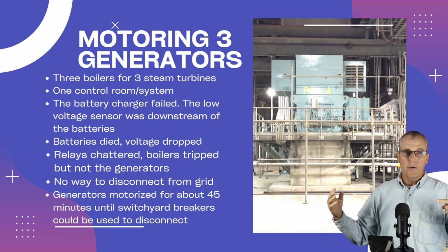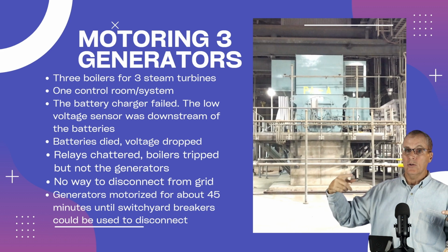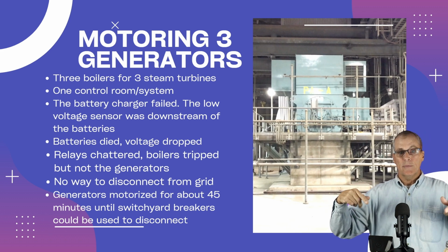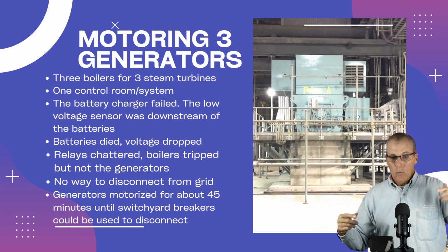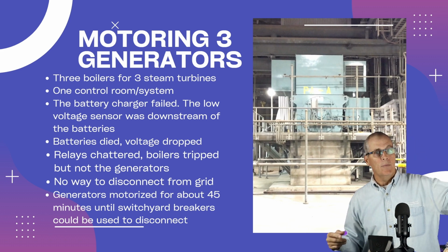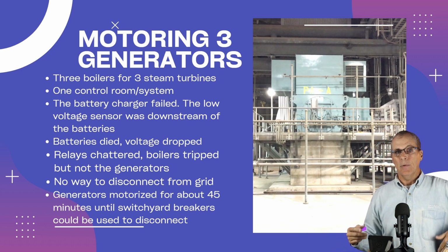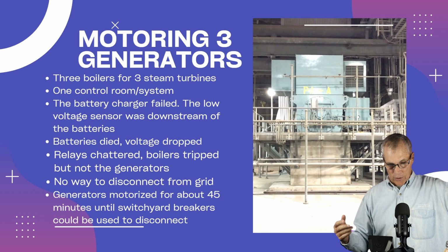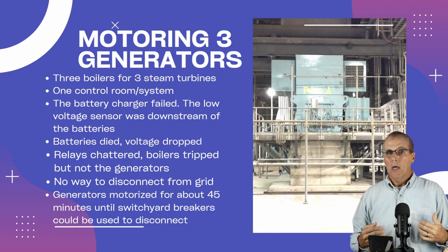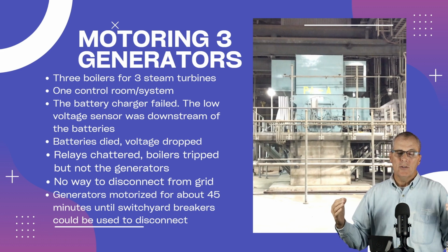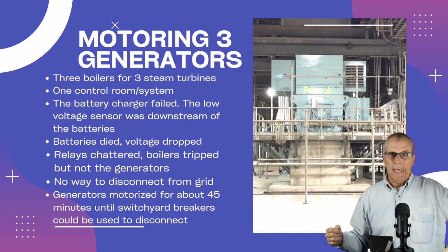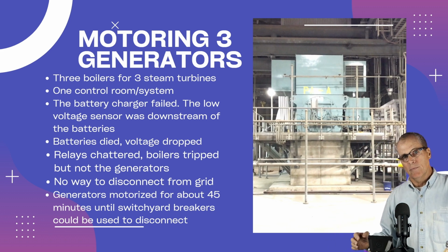Well, with no steam going to the turbine, the grid pretty quickly started motorizing that generator, spinning it backwards. Well, that will overheat the steam turbine because remember, there's no steam cooling it down. Believe it or not, steam is the coolant when it goes through that turbine. I've seen motorized generators actually burn the paint off of the casing of the steam turbine.